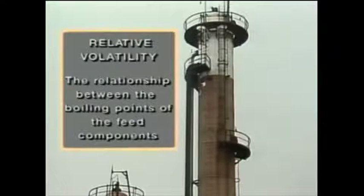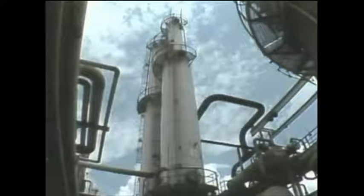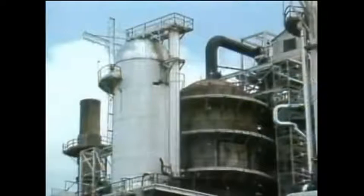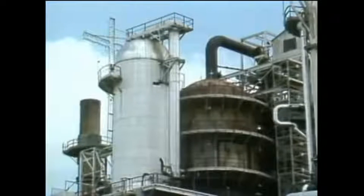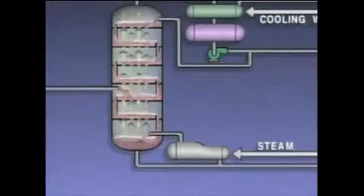The second factor that affects the physical dimensions of a tower is feed rate. Basically, higher feed rates require towers that are larger in diameter. The third factor that affects the dimensions of a tower is vapor loading. Vapor loading refers to the total volume of vapors generated by the reboiler, and the vapors produced as a feed enters the tower's flash zone. The flash zone is the section of the tower where the feed enters and some of it vaporizes. Higher rates of vapor loading generally require a larger diameter tower. Lower rates of vapor loading can be handled in a tower with a smaller diameter.